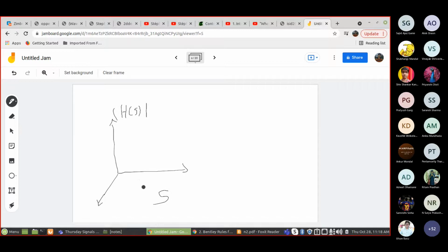This is your S plane, real part and purely imaginary part, and the magnitude is what we are plotting against these complex numbers. Suppose we have a pole at this point. I'm explaining why it is called a pole. At this point the response goes to infinity like this. So imagine this in 3D.